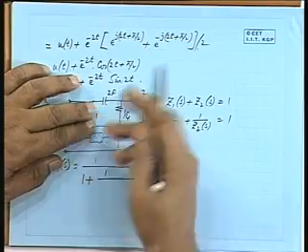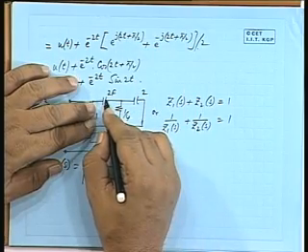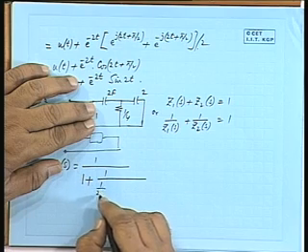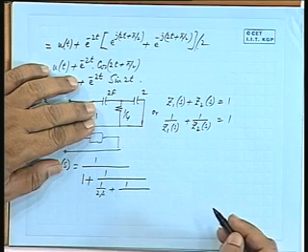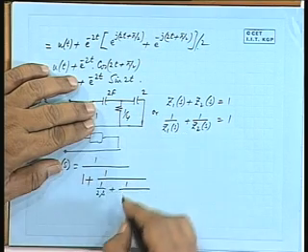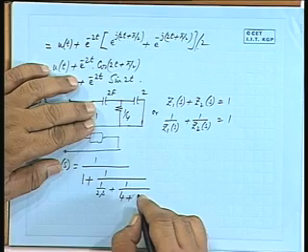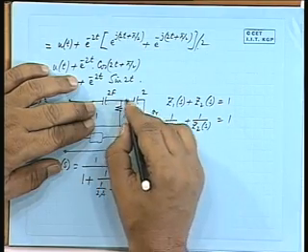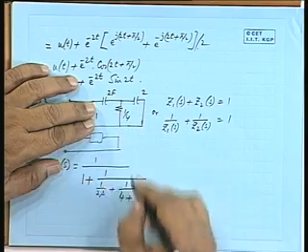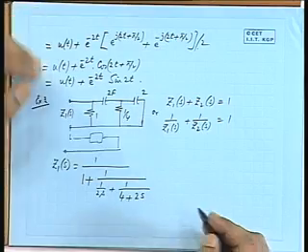If I take out 1 more, then again whatever is the balance, if I write in the impedance form, then it will be 1 by, 2 farads means 1 by 2s, plus 1 by 4 mho plus 1 by, so this plus this, now this is the last element left. What is the admittance of this? These are basically 2 admittances, so 2s. 1 by 2s, that means 2s.